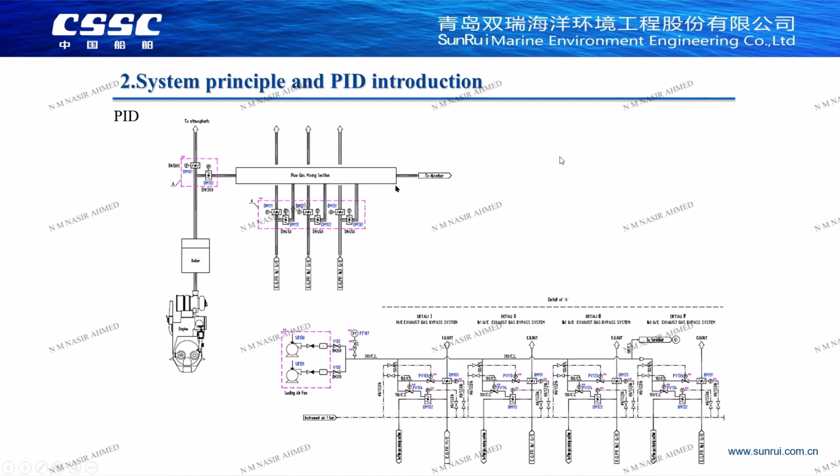This is a simple piping diagram of the waterway. This part is the piping diagram of the ship's smoke. The flue gas we mainly clean includes the exhaust gas emitted by the main engine and 3 generators. Take the main engine as an example. It will have 2 smoke valves. One is a direct discharge outboard as a bypass. The other way is into our desulfurization tower for washing.